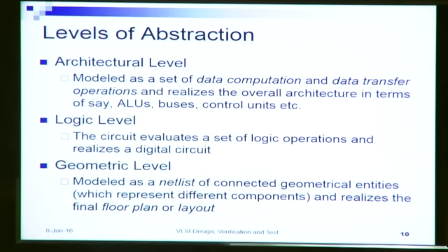Then we come to the logic level. At the logic level, the circuit is represented basically as a set of logic operations, or let us say a state machine with respect to a controller and a set of Boolean equations that represent the register transfers that happen.